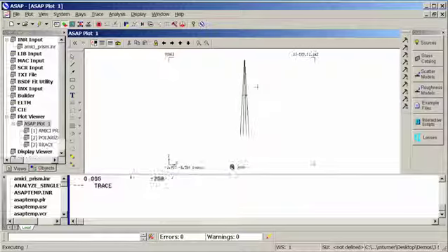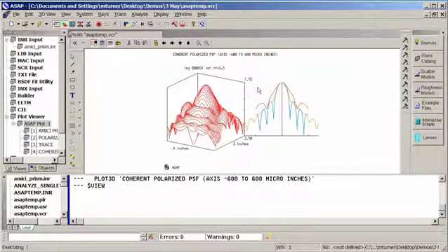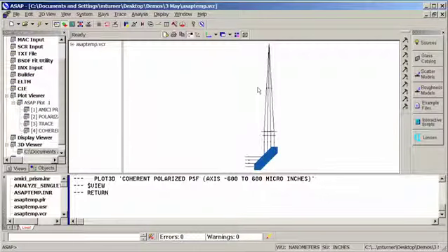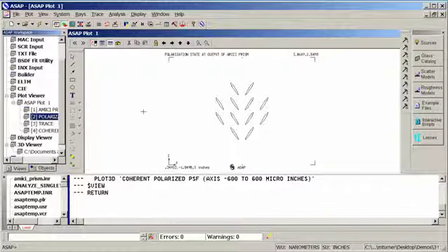In this particular case, we're actually going to propagate the wavefront in steps. First, we're going to propagate the wavefront simply through the prism and take a look at the polarization state. Then we're going to propagate the rays the rest of the way through the system and take a look at the image results. So again, initially we'll just propagate through the prism and take a look at the polarization state after the light is propagated out of the prism. And we can see that our input linear polarization state is now elliptical.